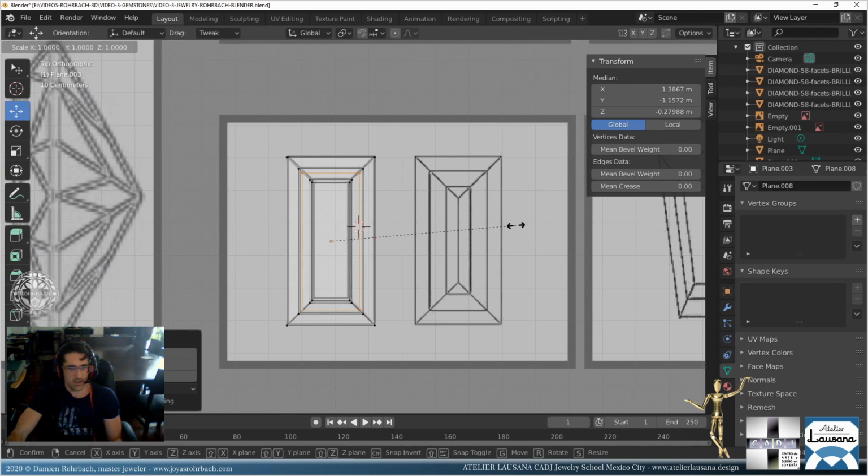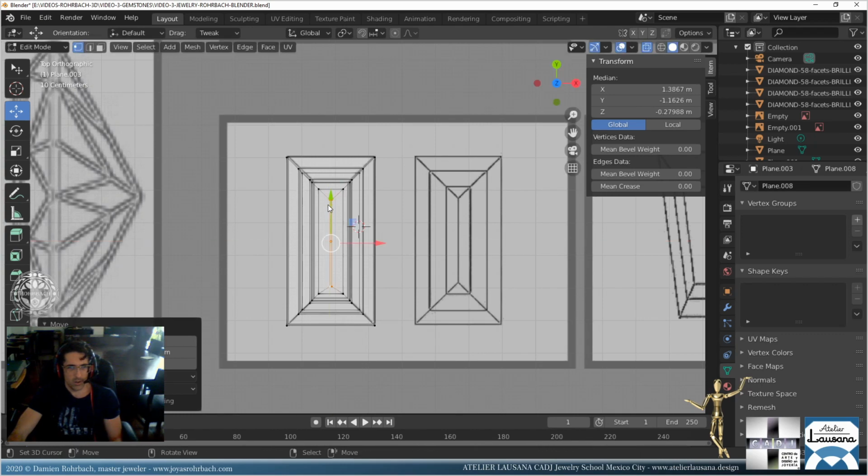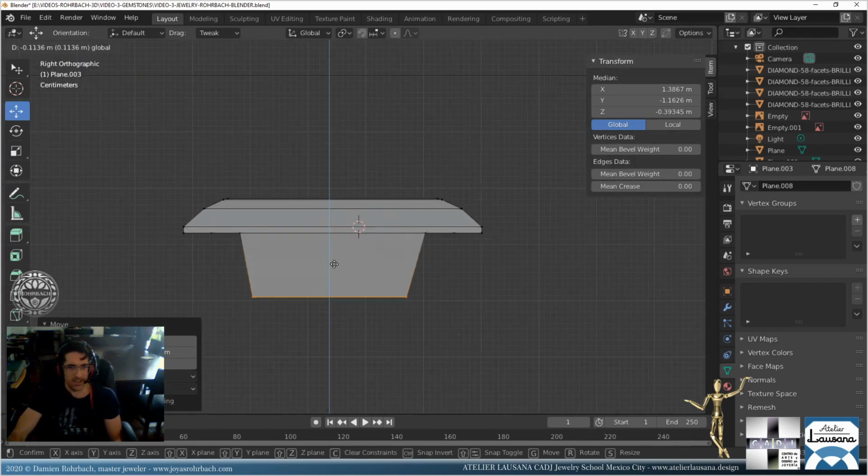Let's do an S. No, excuse me. Extrusion, scale. That one goes to the middle like there. SY. Let's keep the alignment on the diagonals. That's that one. Extrusion scale. SY. Always keep. Okay, that's perfect. SX to make it a bit more. Now just check, obviously, the levels.